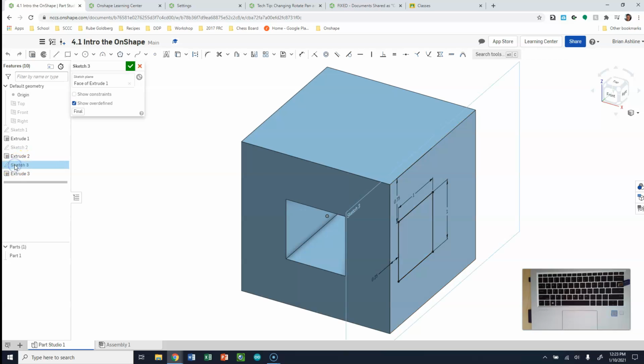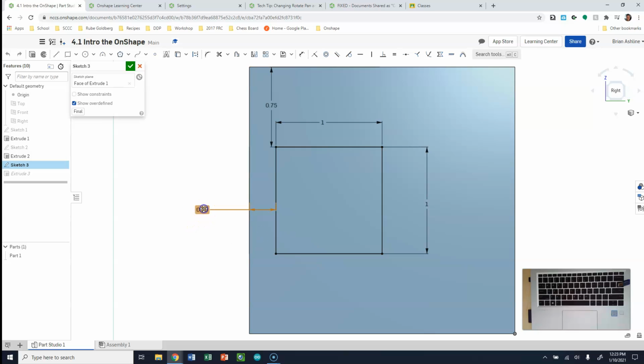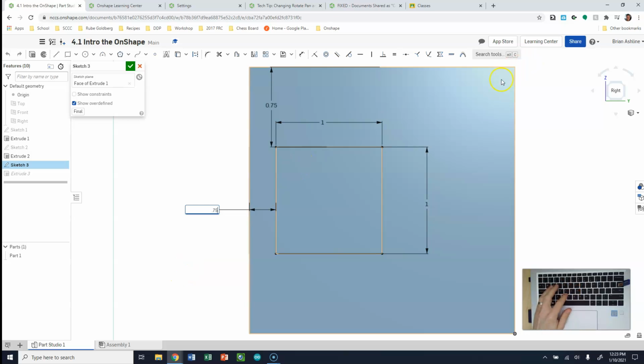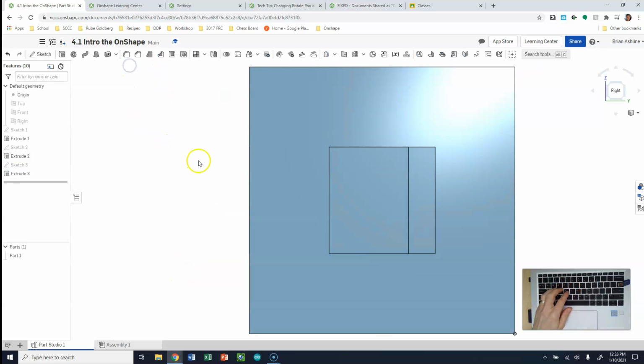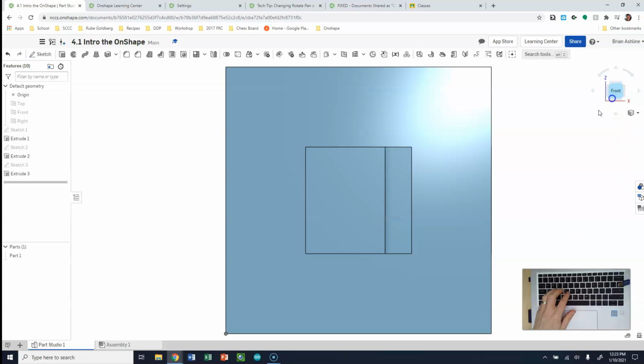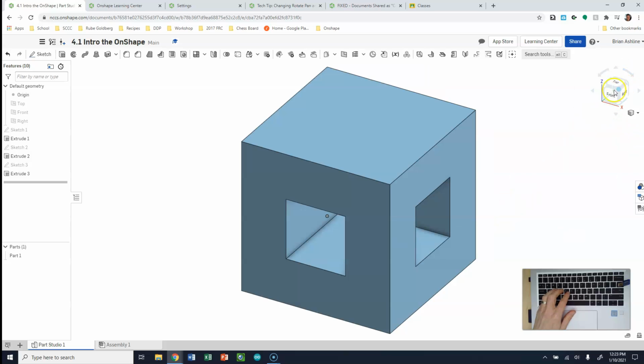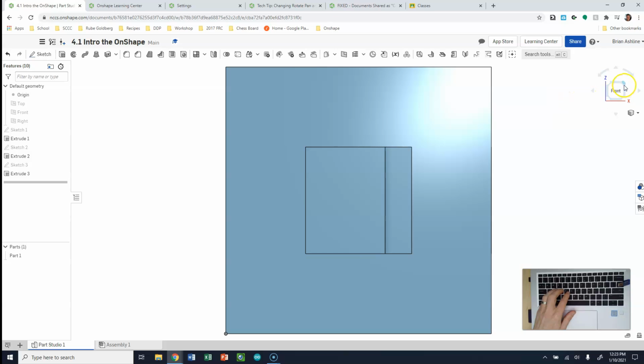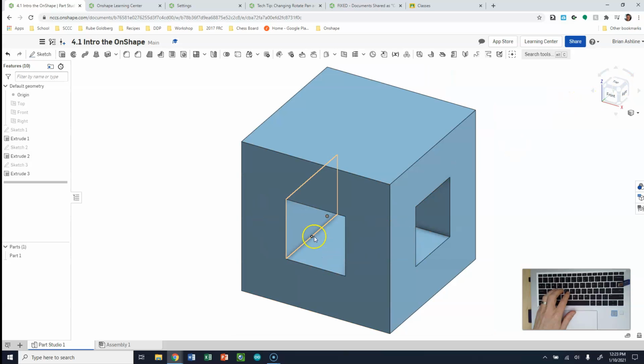So we're going to double click on sketch 3. And instead of this thing being set to 0.25, we're going to set this to be 0.75. Okay, and center it in this 2.5 inch object. And we are going to come out of that. Okay, and the one last thing that we need to do is this first object isn't cut through far enough. Okay, this first hole here. So we're just going to edit that real quick and make that go all the way through one last time.